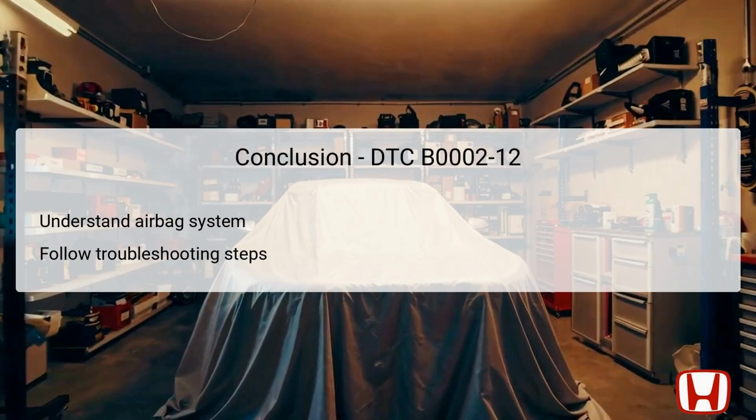In summary, DTC B0002-12 relates directly to a short-to-power condition in the driver's airbag second inflator. Understanding the entire airbag system's components, like the airbag itself and the SRS unit, is crucial for efficient diagnosis and repair. Following the detailed troubleshooting steps ensures a systematic approach to identifying the root cause of the problem.